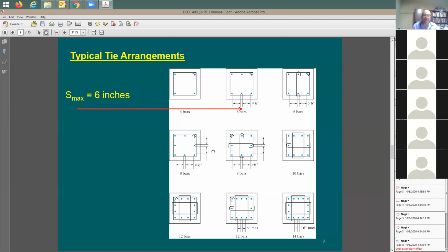This gravity column is going to be riding with you. I mean, it's true, when the building is going to be moving, all the columns are going to be moving with it. The columns that are supposed to resist these movements, and also the columns that are just already there, but they have to move with the building. So you're kind of bending them. You apply here some moment to them. Whether you want it or you want them to resist it or not, you don't want these columns to be failing because of the amount of cracking in there. So in California, seismic code, they have certain provisions for gravity columns. And this is going to dictate here the number of ties that you need to provide.